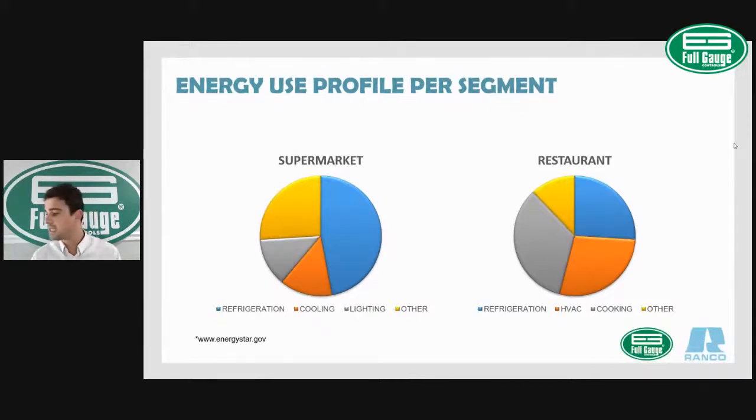In addition to that, once the electric heaters are on, they draw a lot of electricity. Also, some of the heat created at the coil gets transferred to the refrigerated space, and eventually you have to remove that heat from the refrigerated space. So there is another energy expense right there. To sum that up, that's the importance of having a precise and efficient defrost cycle to optimize your energy consumption and increase the life cycle of your equipment.